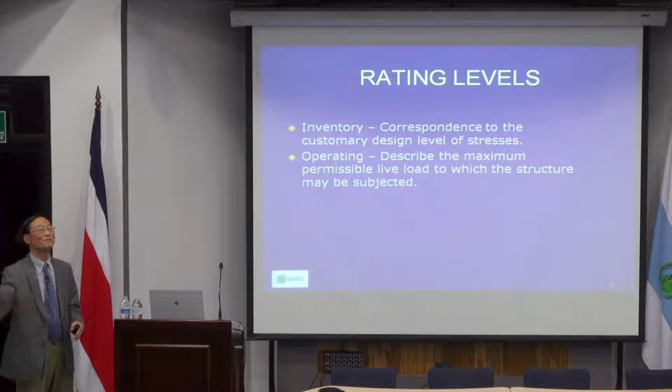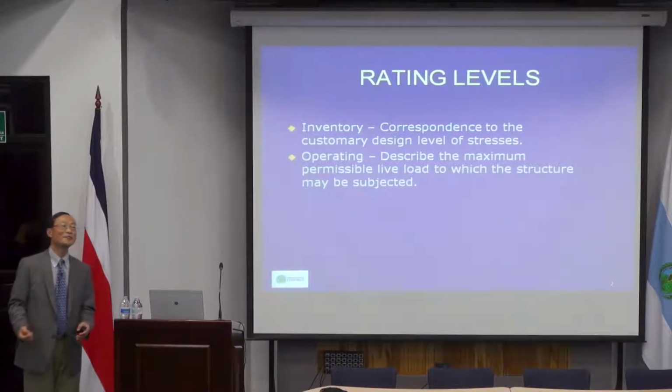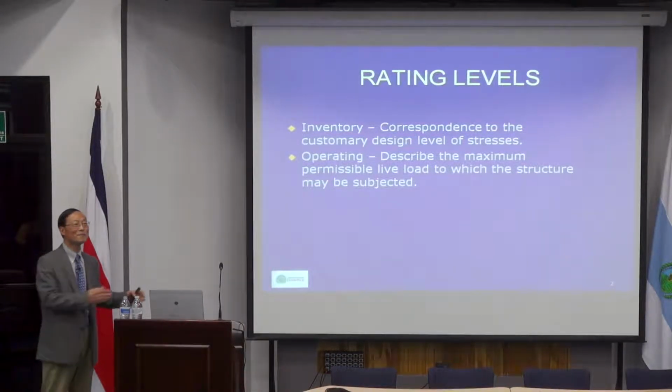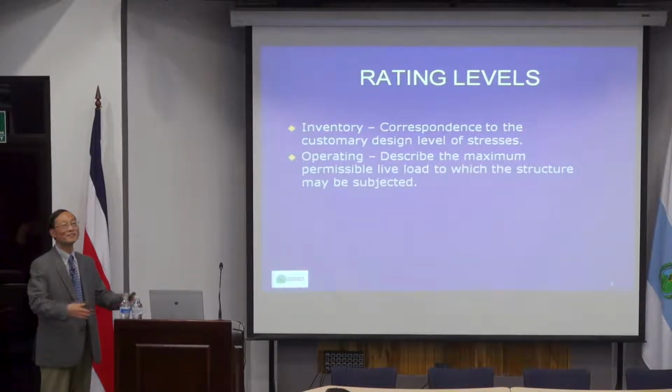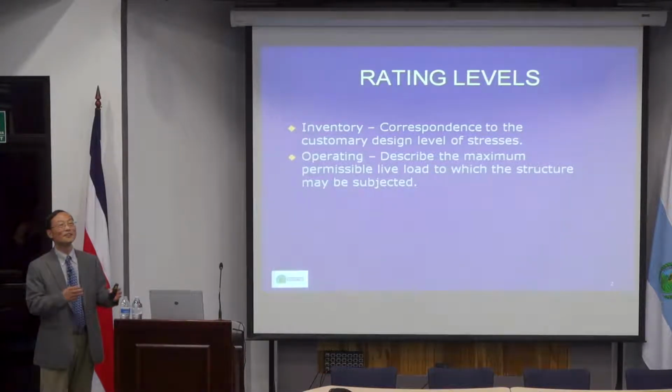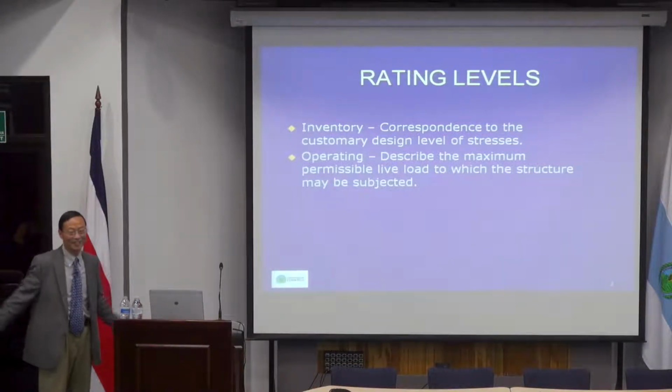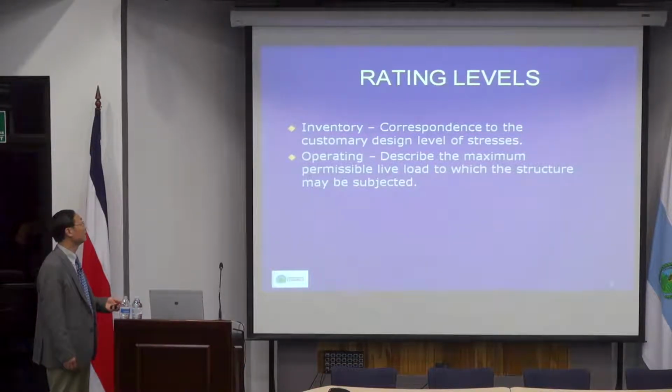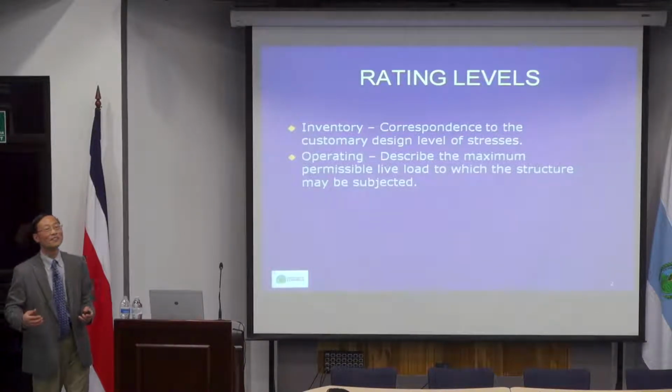If the safety factor is too big, you have a much smaller probability of failure, but then you waste a lot of material on every bridge. That may not be a good choice. You may rather compromise and say, okay, I can have such a small probability of failure so that I don't have to design every member so big. So that's when you design, that's only one level.